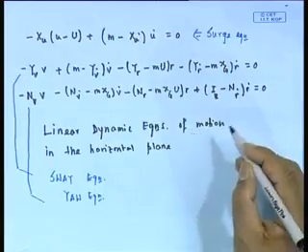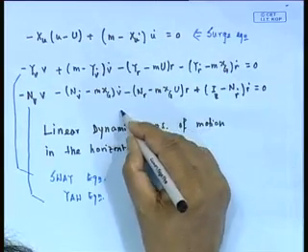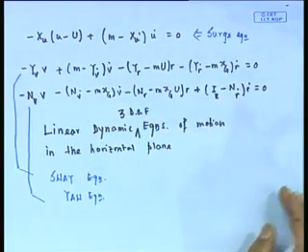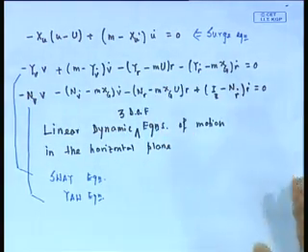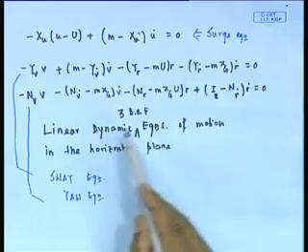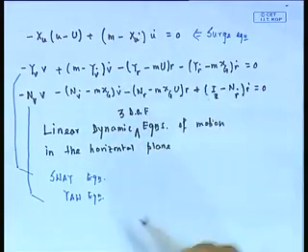I would write 3 degree of freedom, meaning here I have got only 3 modes where I am allowing the ship to move. This is the simplest one that you have to have. You could also have a little more complicated one. For example, if I allow the ship also to roll, because when it turns it might also roll, then I would have one more equation, the roll equation of motion. Then I would have a 4 DOF equation of motion, etc.